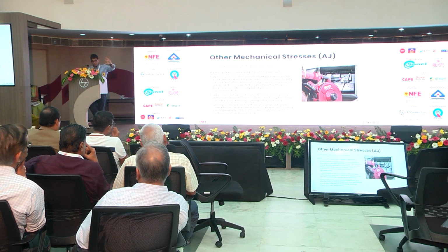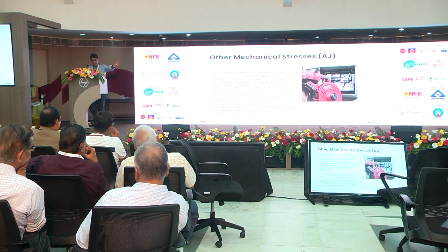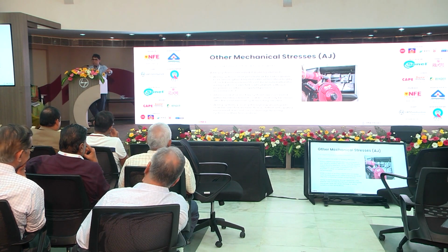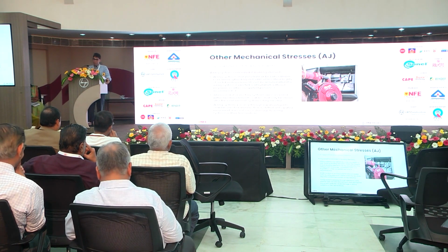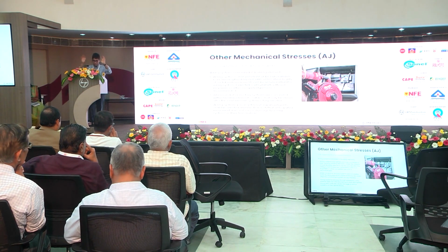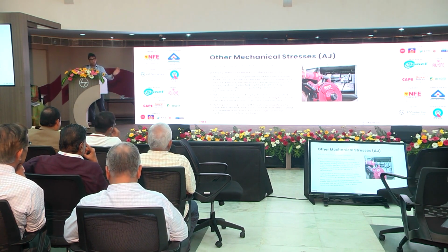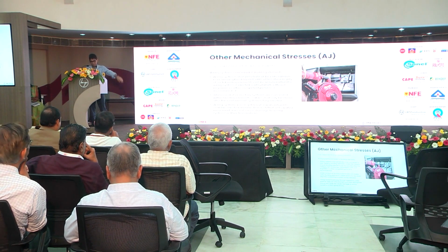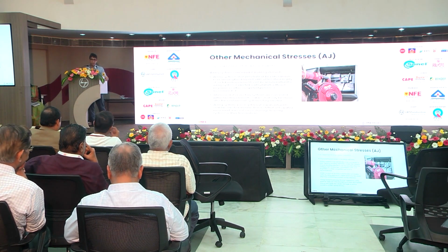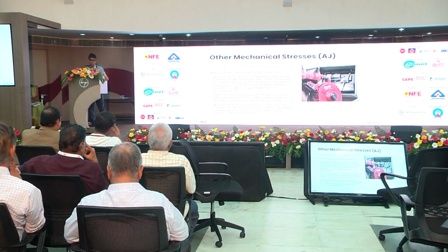And then even just inside walls, the ducting and conduit systems need to be fully erected before you put the wiring through. I have not seen any electrician that actually does this. They all run the cable while they put the conduit and then they pull it. The reason for this is A, you are more susceptible to mechanical damage when you do it together, and B, if you put the cables inside and you're done, how are you going to contain maintenance if you want to make any additions, alterations? That cable is just not going to come out.